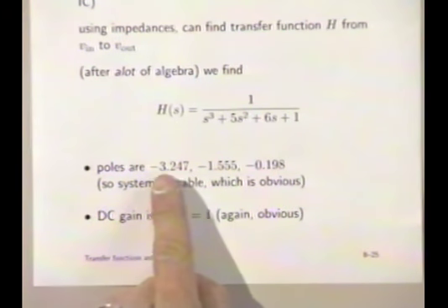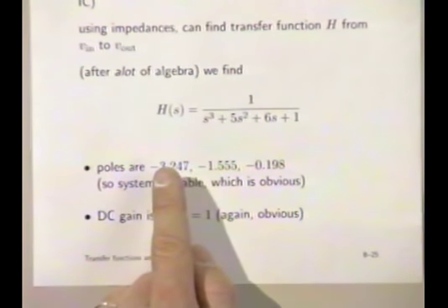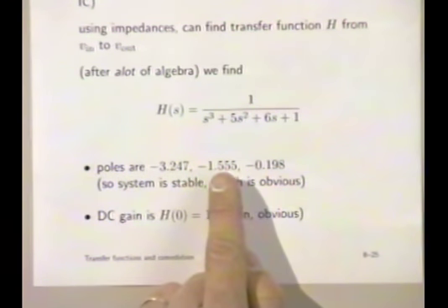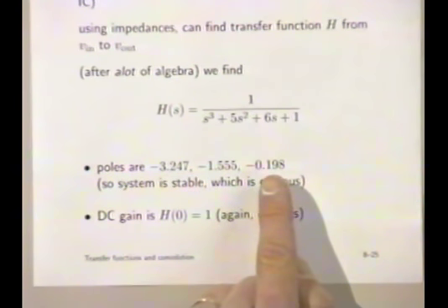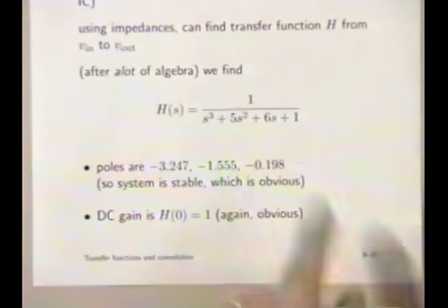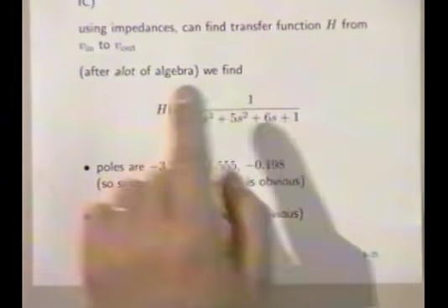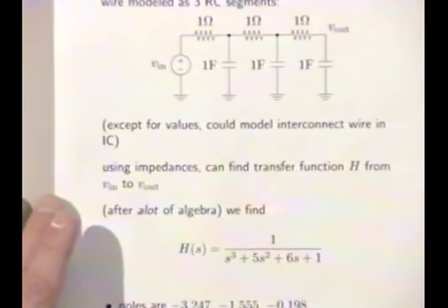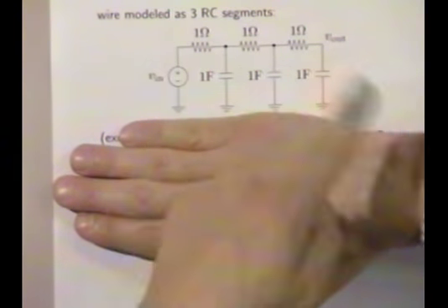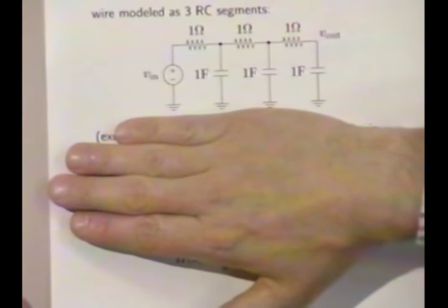So this corresponds to an exponential that decays on the order of a second or so. This one is one that decays on the order of 2 seconds, let's say. And this one decays on the order of, I don't know, well, more than 20 seconds, 30, 40. No, sorry. 1 time constant would be 20 seconds, so maybe on the order of 80, something like that. So this is 80 seconds. So this is the one that really drives the time constant of the whole thing. And in fact, it's interesting to get a rough idea. If someone showed this to you and asked you what are the time constants,